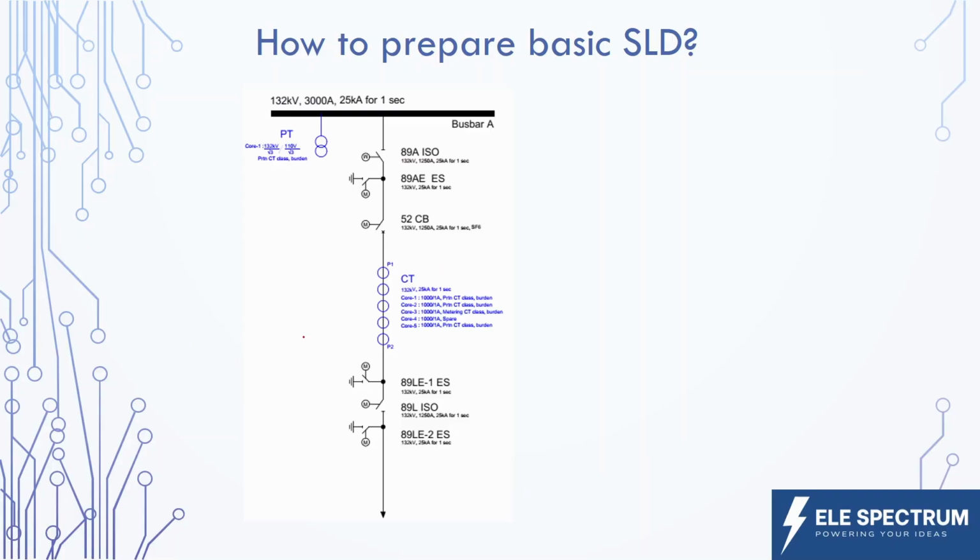And the potential transformer is a shunt element, as we just need to detect the voltage. These are generally placed at the bus bar also, and can be used for the protection and measurement purposes. And this potential transformer sometimes can also be placed at the transmission line. There is also another variant of this voltage transformer, which is called CVT, capacitive voltage transformer, which is also used for power line carrier communication system. Regarding this topic, we will discuss in another video.